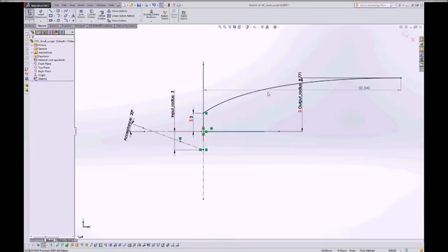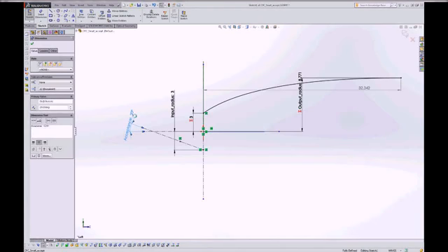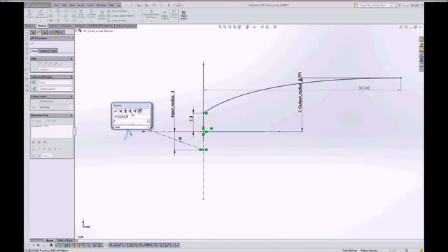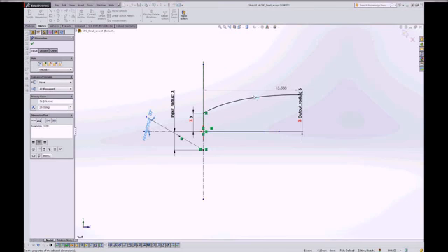So what I've done is created a CPC structure that I can use over and over again simply by changing the parameters to those that are appropriate for the design I want to work on. In this particular case, I do want that 30-degree cone. Okay. So to turn this into a CPC, all I have to do is turn it into a revolved surface.